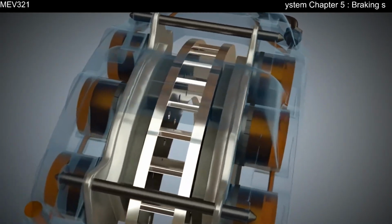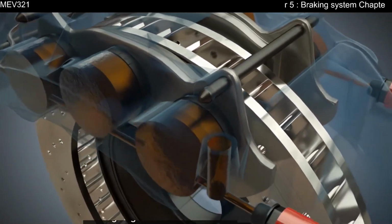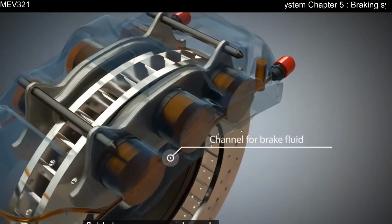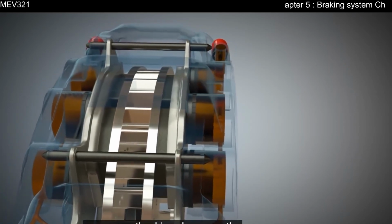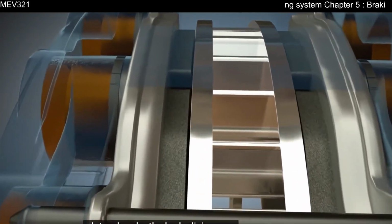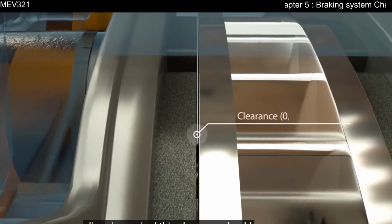Caliper pistons are controlled by brake fluid and sealed with the help of sealing rings. Brake fluid enters the channels of the caliper via a hydraulic connection. The caliper pistons on the opposite side are supplied with brake fluid via one or more channels. As soon as the driver depresses the brake pedal, pressure is exerted on the brake fluid. This pressure then presses the caliper pistons against the carrier plate, whereby the brake linings are pressed against the brake disc. To prevent continuous grinding, a minimum distance between brake lining and brake disc is required. This clearance should be approximately 1 millimeter.